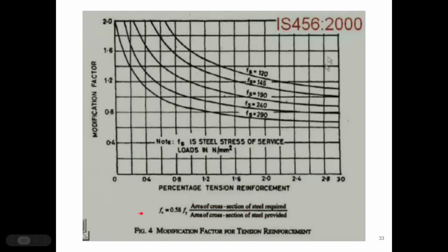So the steel stress at service, fs, is 0.58 into fy into Ast required by Ast provided. Using that you can get the fs value.